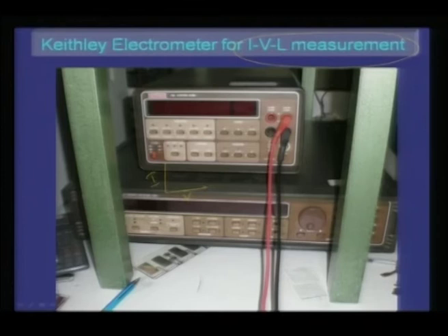So, if you are making an organic LED, your electroluminescent device typically will have some feature like this, where up to a particular voltage there will be no current, and at this threshold voltage you will see current flowing. That means your electroluminescent device is going to produce light. Light will start appearing after you have applied a threshold voltage.